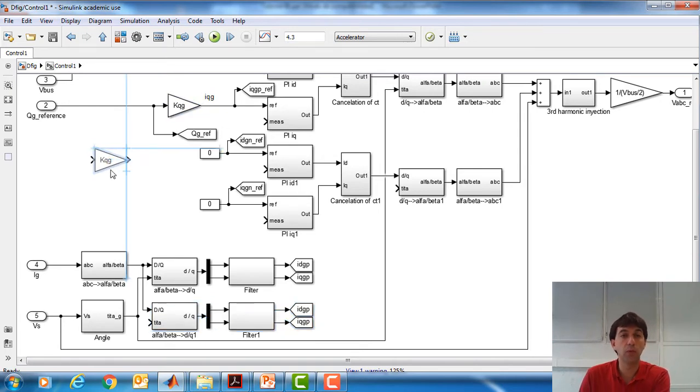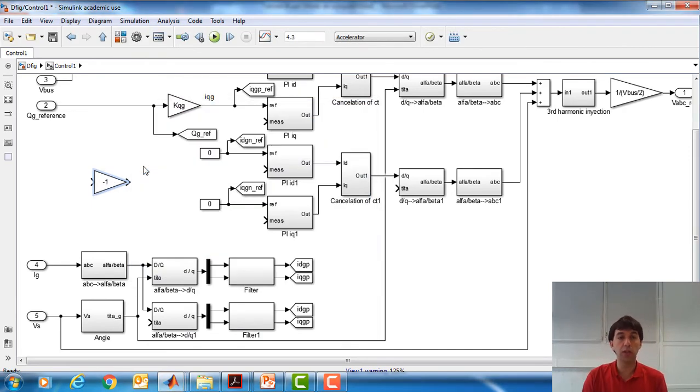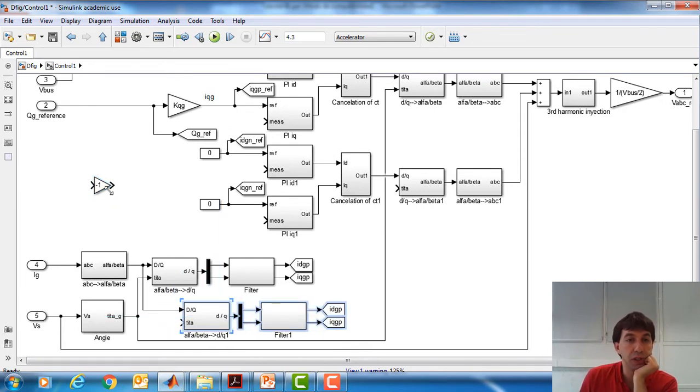So we need one gain like this, and we just need the opposite rotation sense of the space vectors. Therefore we need to put a -1 just in the angle. We will need some more space. Let's do it there. And this is theta, currents theta minus theta.